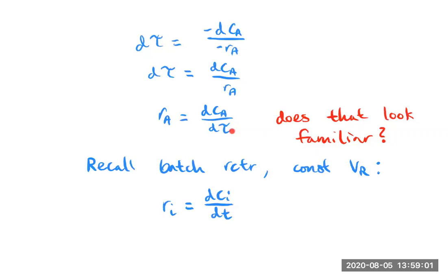I wanted to make a point here. Part of the reason why we like residence time, which I think is better illustrated in this example than in the CSTR example when I first brought it up, is that at least in the case of a PFR, it allows us to put the design equation into an almost identical format as batch reactors.